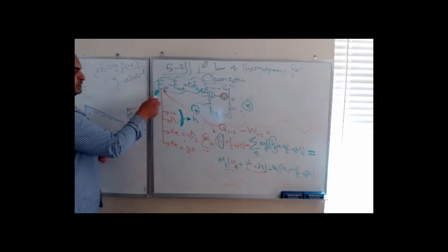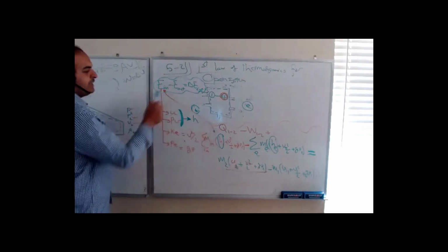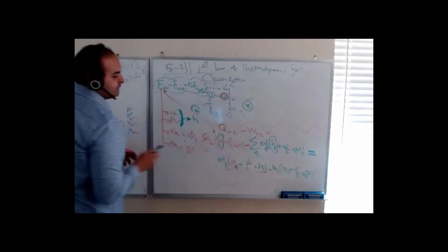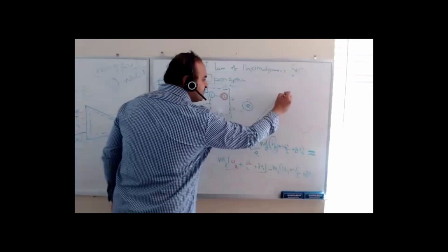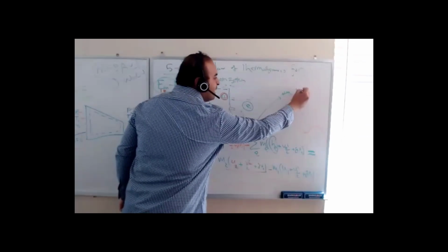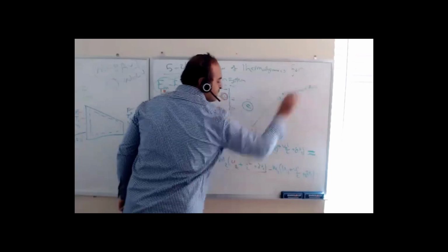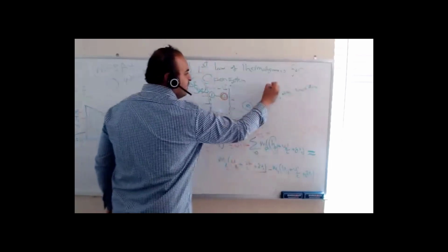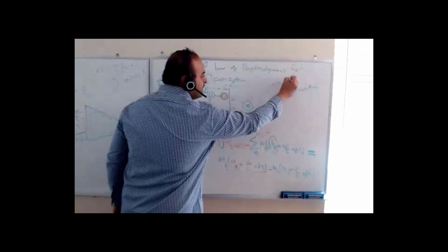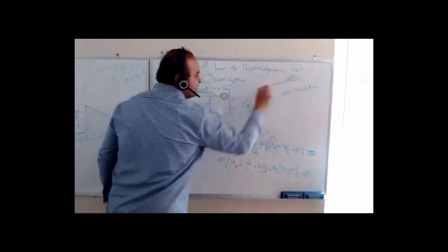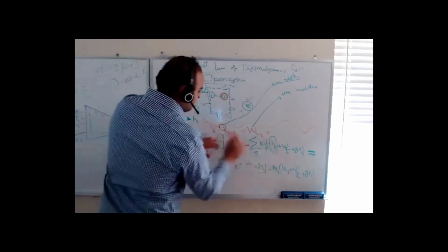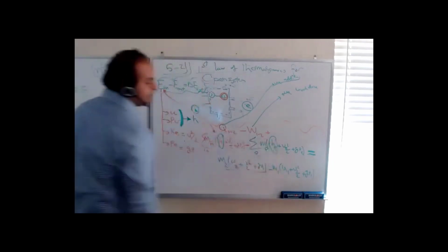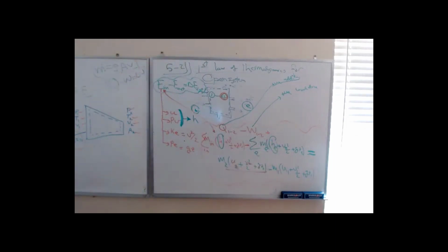So energy input, for example, we have Q. Energy output, for example, we have W. So W, by definition, is positive if it's work done by the system. Q is positive if it's heat addition to the system. This is a positive sign, the same as the first law. So if this is 0 and this is 0, Q minus W equals delta U. Correct?